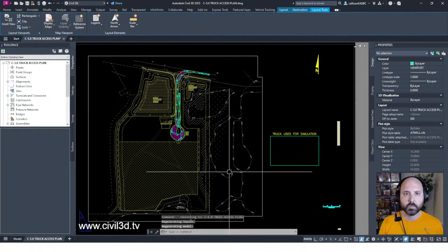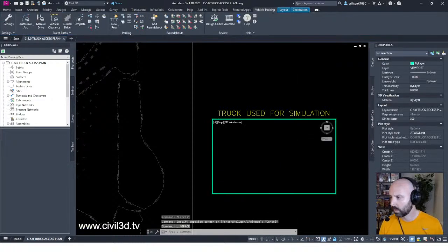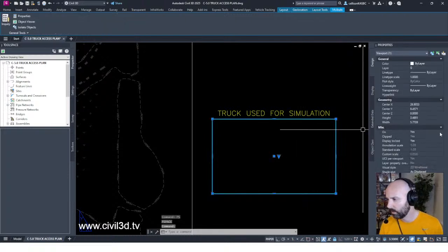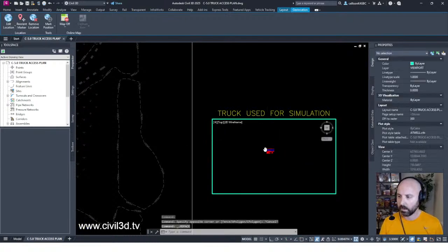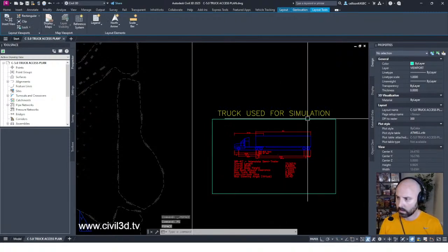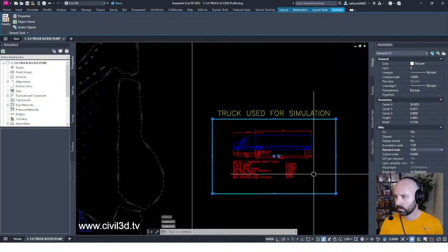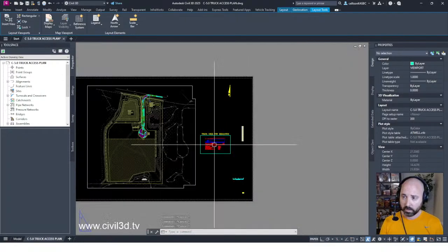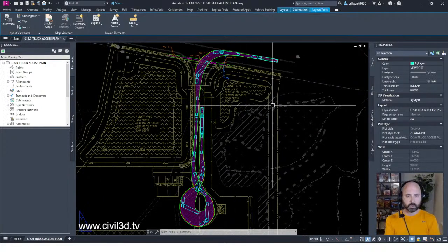And then within our viewport, I'll come in here. Is this a locked viewport? Locked viewport, yes, it is. I want to unlock this. I'm going to zoom out. There it is. Zoom in a little bit. Make this standard scale of 20. And there you go. Kind of gives you some dimensions of what you're dealing with. And there you go. Okay.